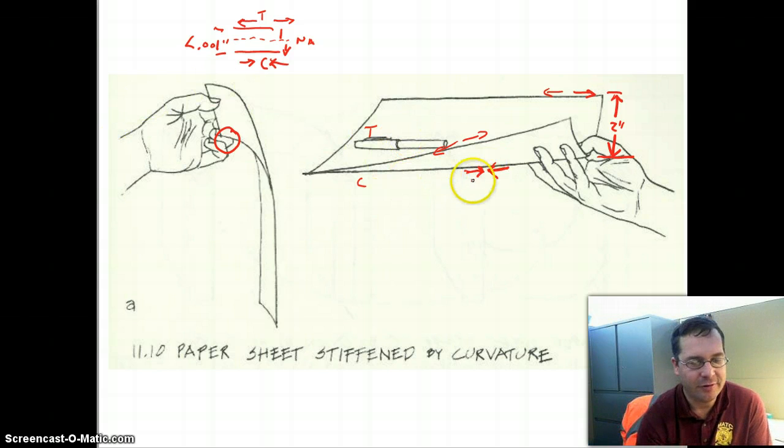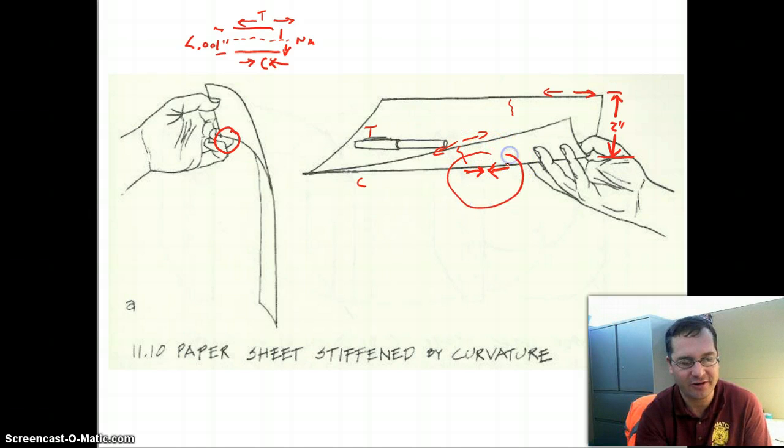Incidentally, this is kind of a good illustration of slender structures. We know that we're not likely to tear this paper, right? It's not real likely that we're going to develop tensile cracks in the top of this. What's far more likely is that we're going to have a buckling type failure down here on the bottom, which is a characteristic of slender structures, and we'll talk about that some more when we look at Euler's columns, which was a prediction of, he predicted basically that columns would fail in buckling once they got sufficiently long and spindly.